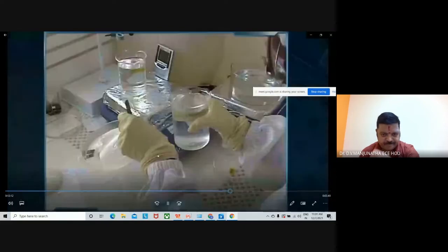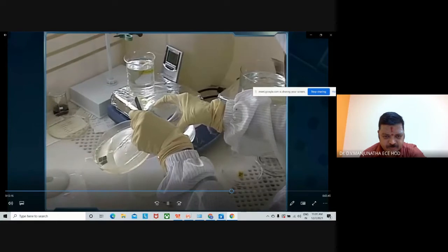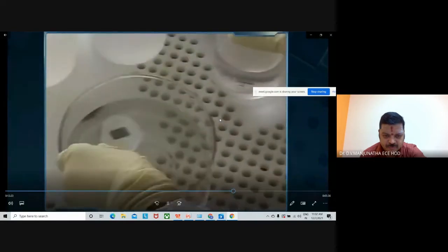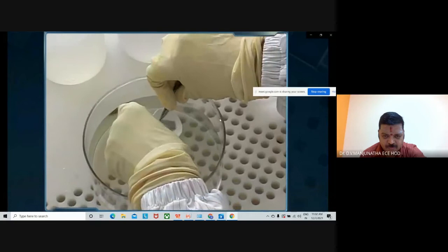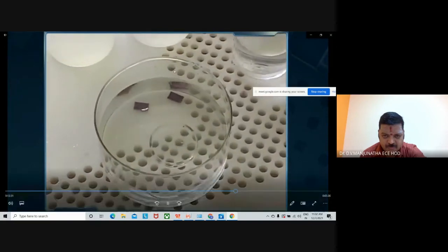This is followed by a rinse with DI water and isopropyl alcohol. Here, care is taken to let samples remain in liquid. Otherwise, chances of stiction, or cantilevers sticking to the substrate, are high.